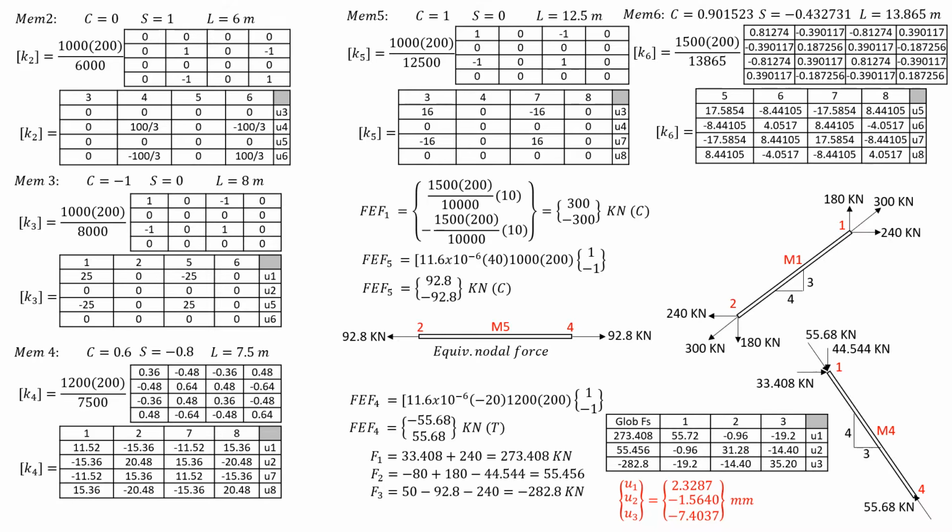That's for displacement. Then for the member forces P1, P2, P3, P4 for member 1, we have AE over length times the cosine of member 1, negative 0.8. The sine is negative 0.6. Then the negatives of negative 0.8, negative 0.6, 0, 0, 0.